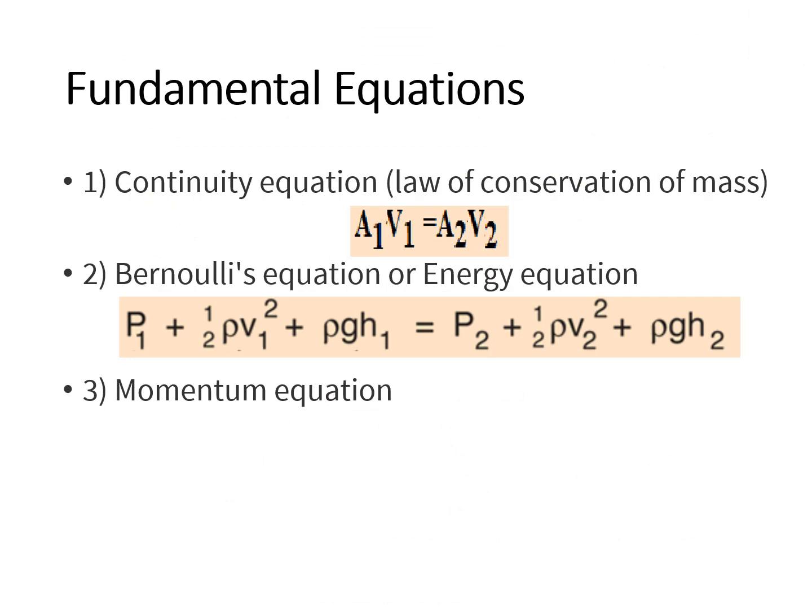When we look at the fundamental equations governing the flow of liquid in open channel flow, we have the continuity equation, which is based on the law of conservation of mass: A1V1 equals A2V2. The second equation governing the flow is Bernoulli's equation, or the energy equation, and the third is the momentum equation. These three equations govern the basic fundamental equations of the flow.